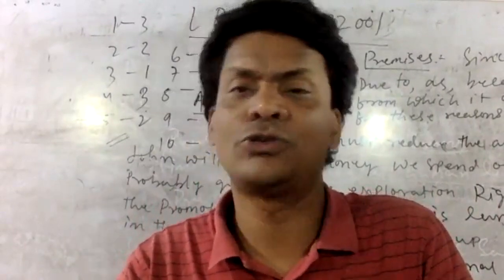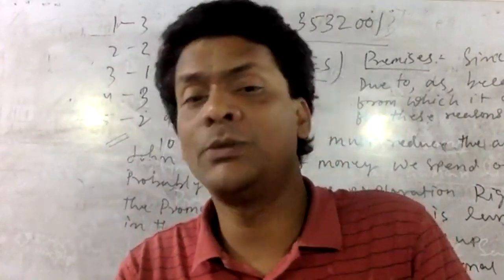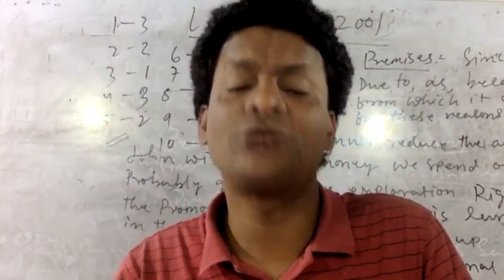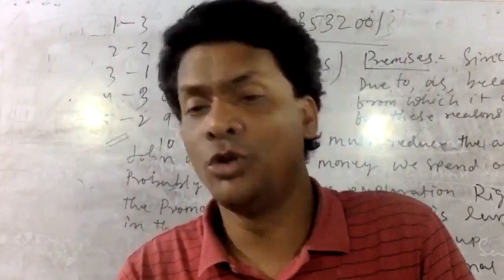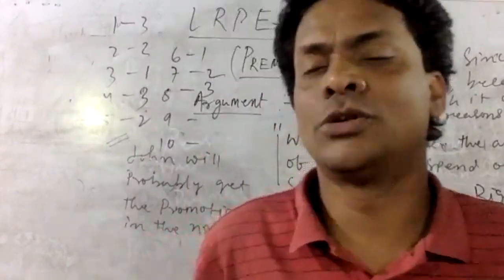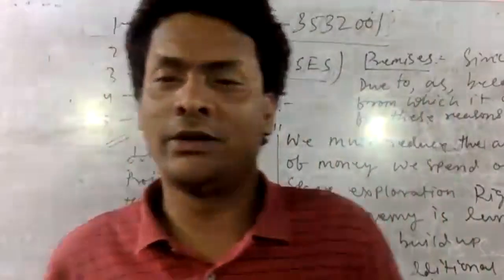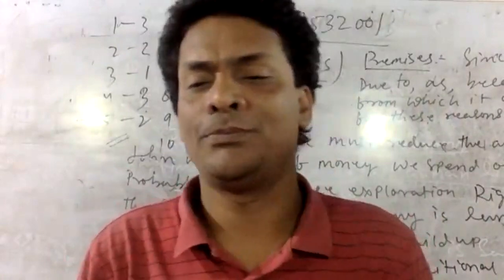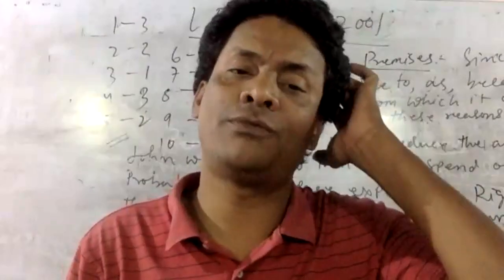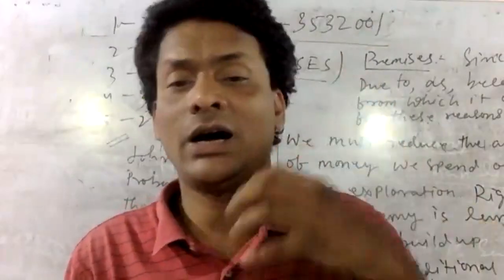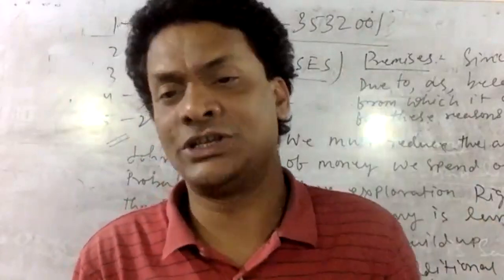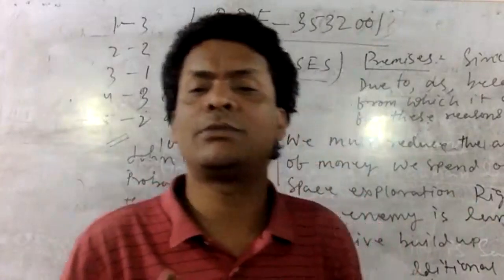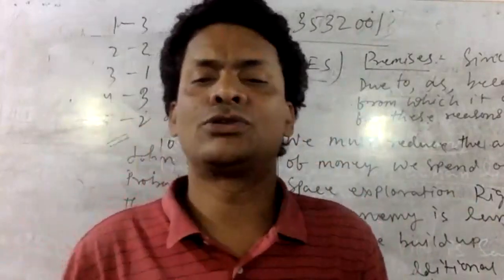Non-ferrous metals are used because of desirable properties, meaning properties that are necessary, such as low weight, for example aluminum; higher conductivity, for example copper; and non-magnetic property or resistance to corrosion, as in zinc.